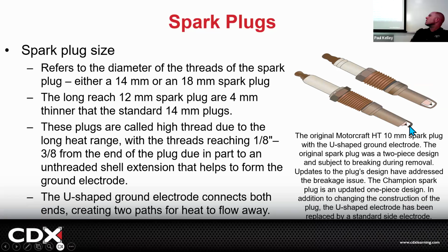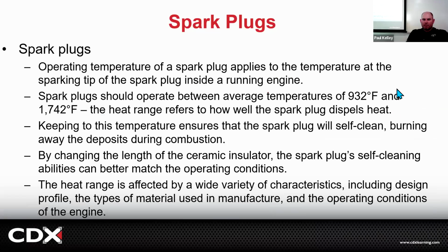But if it gets worn thinner to the point where it's just hanging by a thread, the electrode will actually break off and fall in. This is a stronger electrode. They're having issues with those breaking off and falling in. So that one's better. But then if you get into the Spitfire plugs with 4 grounding electrodes, they have a lot of funky stuff, but I would run what's OEM. They did have these installed in some OEM. So that's legit.